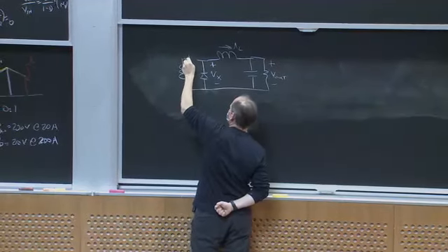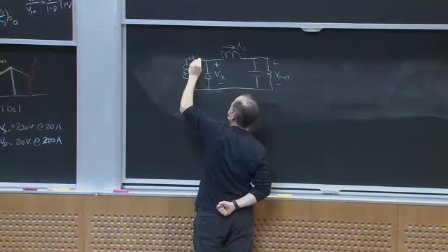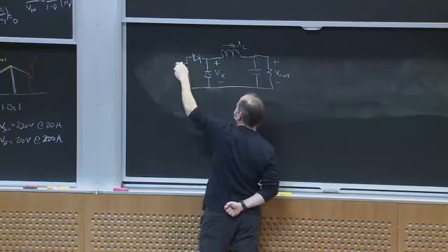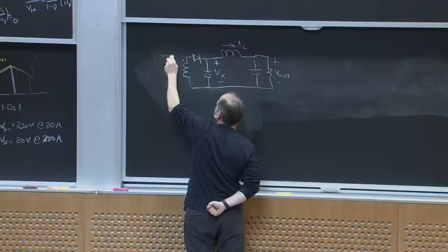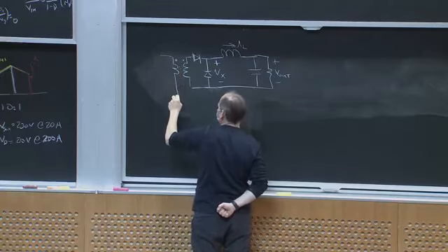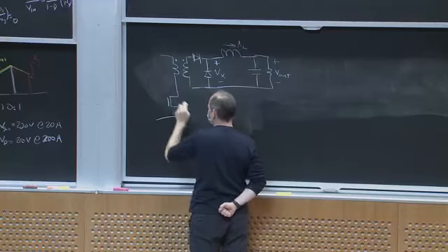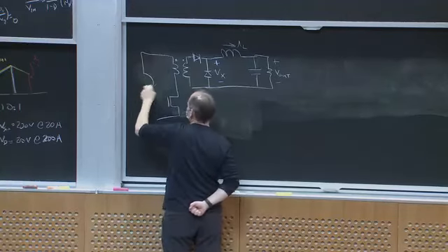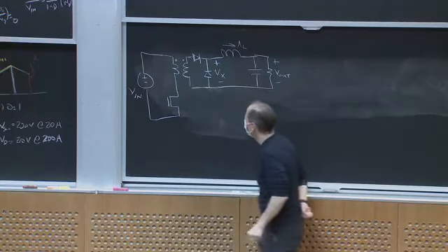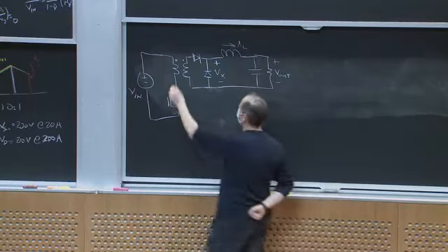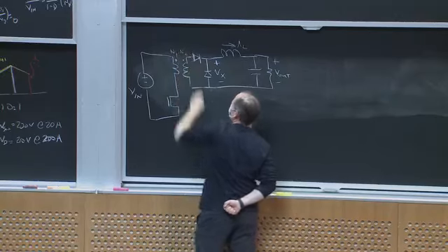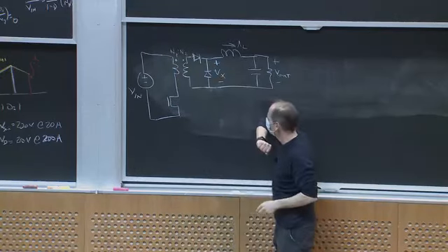It turns out I'm going to need another diode here, because I cannot apply a non-zero average to this transformer, okay? So I need this diode. It's a new diode. And I can play the same game and put my switch as a ground reference here. And so here's Vn, right? So what happens, let me call this N1 to N2, right? So what does Vx look like?